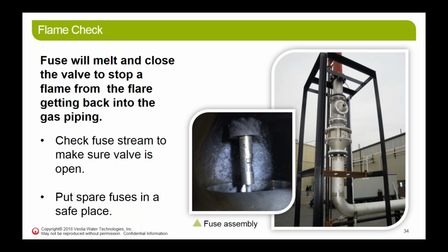The important thing is that when that happens, you have to have a replacement fuse to get the system working again. On the Varec type valves, which one is shown here, I think, they usually wrap the extra fuses onto that nut on the top there. You see the round valve there with a wing nut on it. Make sure you always keep them there, or put them someplace where you know where they are just in case you need one.